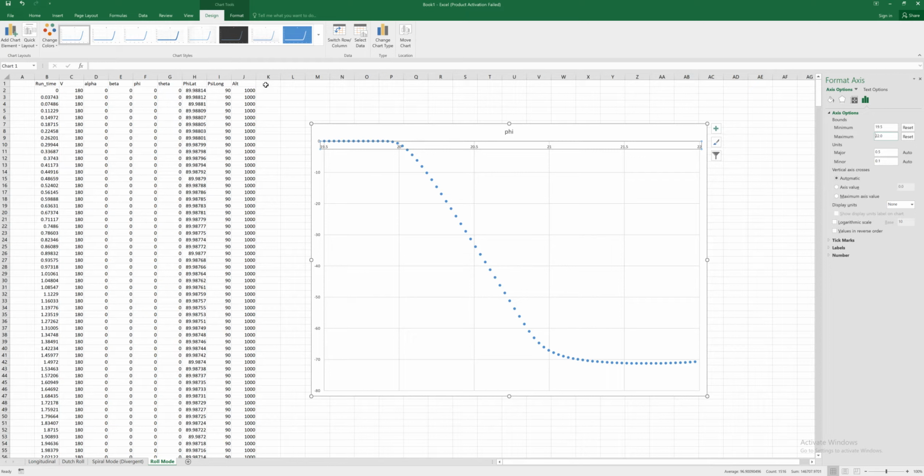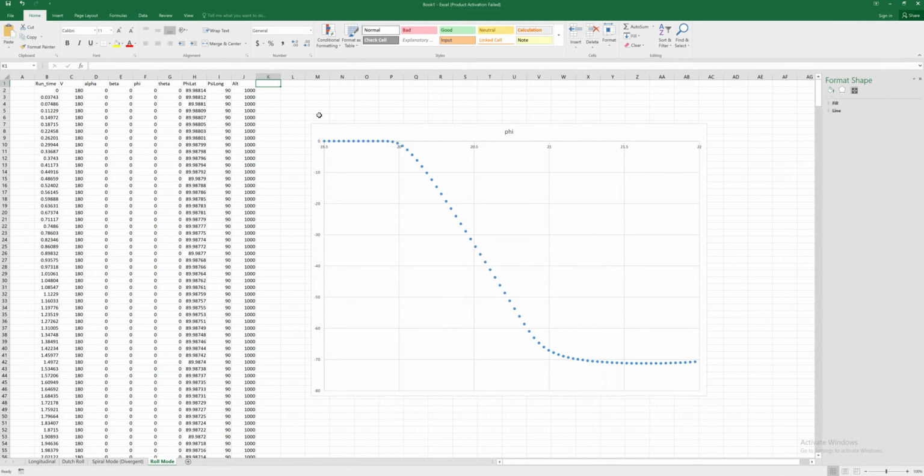So the way I'm going to do that is I'm going to approximate my roll rate. Now, unfortunately, I just didn't have the sim set up to spit out the roll rate. The roll rate is actually something very easily that you can get from gyros or instrumentation on the aircraft. So actually, you would usually have roll rate, but we're just going to approximate it here.